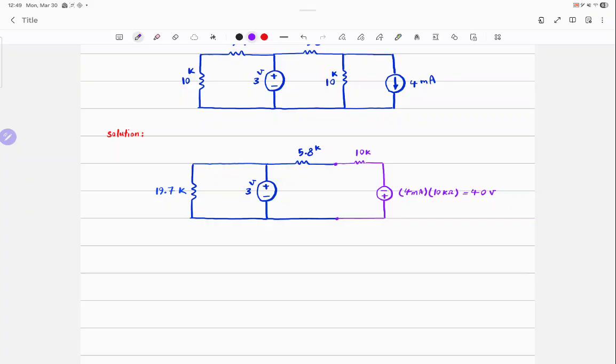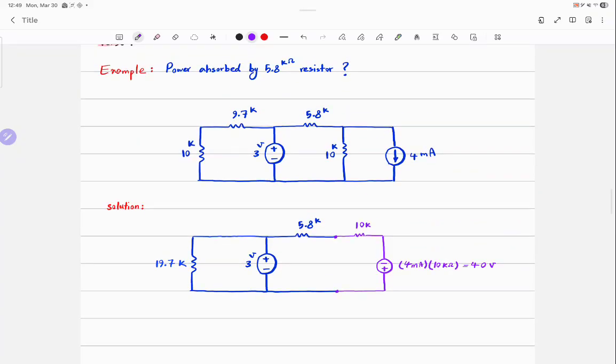The second one is, I'm now simplifying the circuit using source transformation just to practice it with you, okay? Otherwise, I wouldn't do anything to that original circuit. I would just directly go for it and solve it without any simplification, because that source transformation might take, I don't know, 30 seconds, 1 minute, and then the overall time that I spent on analyzing the original circuit would be probably less. So simplifying the circuit is good whenever you see it very obviously and you can do it very fast.